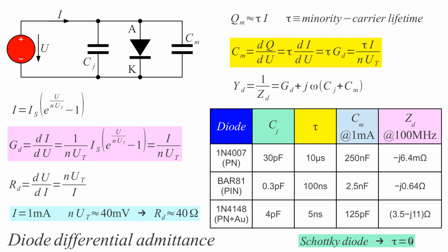And that's the reason why, if we are working with high frequencies, we prefer to use Schottky diodes, because Schottky diodes do not exhibit this effect. They still behave as varactors, so Cj, the junction capacitance of Schottky diodes, is still an important parameter. We could use them as varactors, but the much larger capacitance of minority carriers is nonexistent in Schottky diodes.